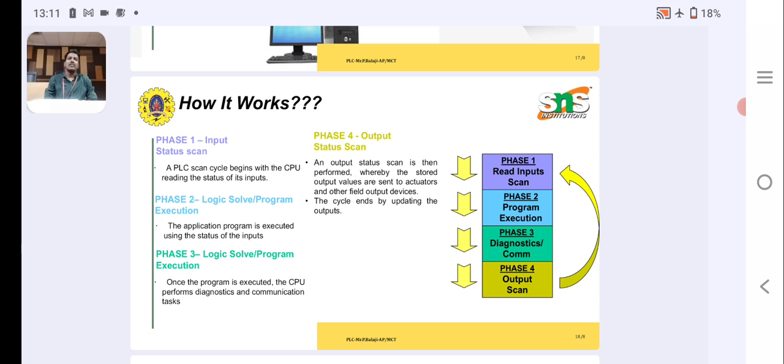Though relatively quick, it is not instant. That means inputs are not watched continuously, but the states are sampled periodically. The typical cycle time is of the order of 10 to 15 microseconds. This means that inputs and outputs are updated every 10 to 15 microseconds. Thus there can be a delay of this order in the system reacting. This also means that if a very brief input pulse appears at the wrong moment in the cycle, it could be missed.